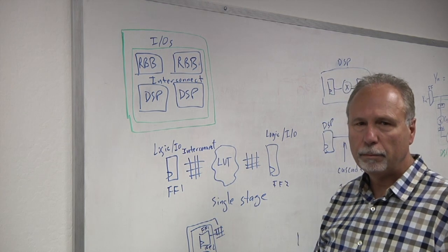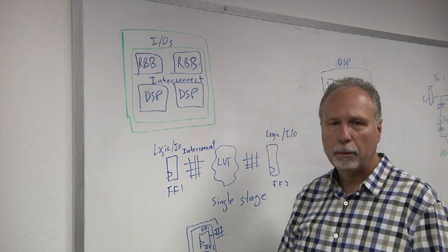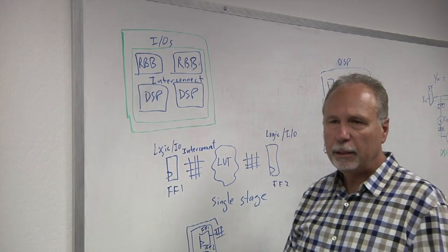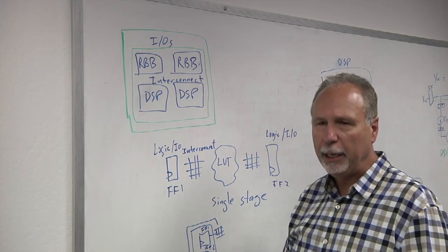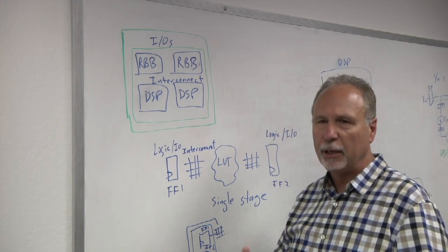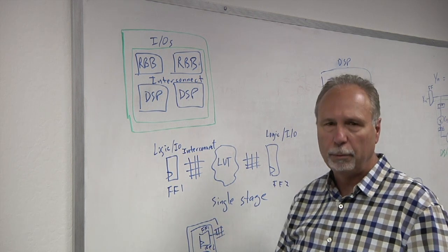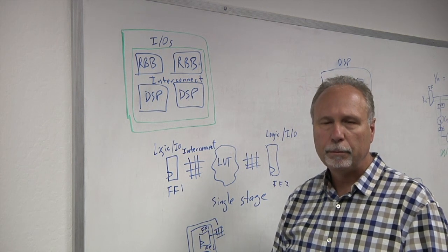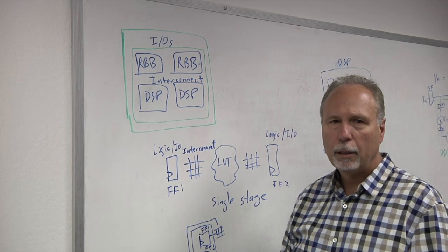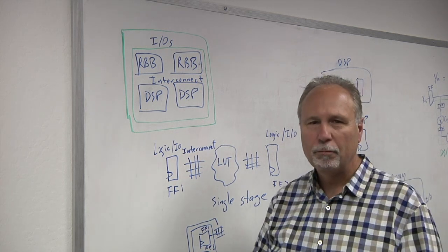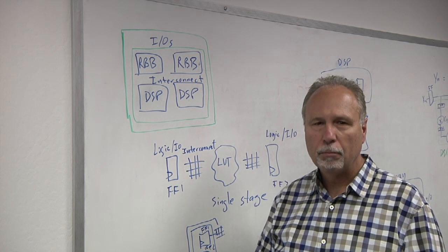And so a DSP is still a separate piece of this, right? It's not part of the embedded FPGA, or is it? The DSP is part of the embedded FPGA. It is reconfigurable, but it's fixed as far as a fixed function, but it's a configurable function. Okay, so this is sort of like an embedded DSP within an embedded FPGA. Correct. So what does this look like in a real embedded FPGA?